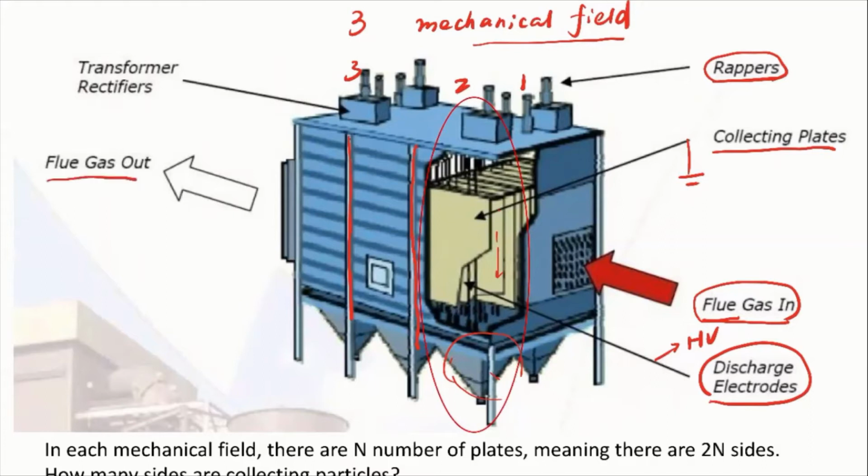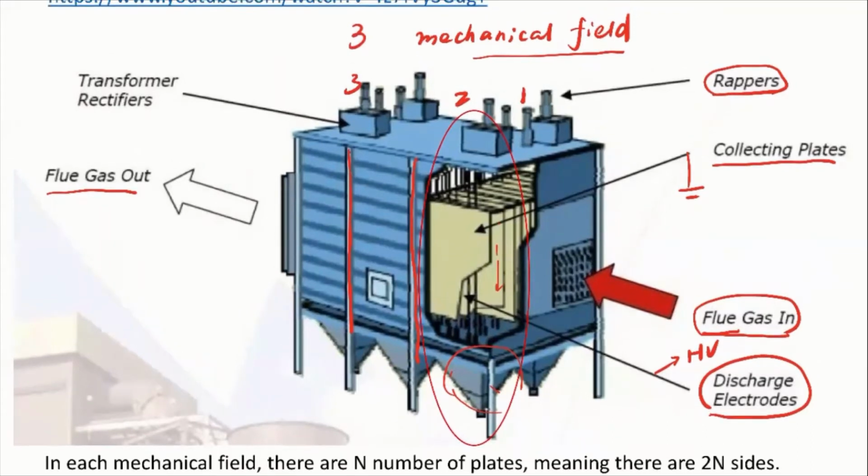And the flue gas out is the remaining flue gas that's been cleaned of the particles. So the ESP is quite efficient. It can remove more than 99% of the particles in terms of mass concentration. Again, we're talking about mass concentration. Recall for the cyclones it's around 90%, right? That's already quite efficient for large particles, but the ESP is more efficient. The ESP also has the problem of a lower collection efficiency for very small particles, but compared to the cyclones, they're efficient enough. Okay.